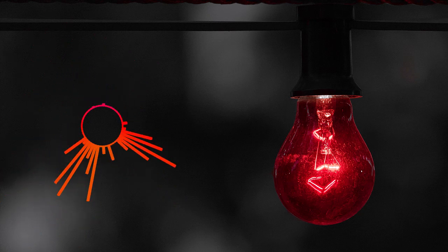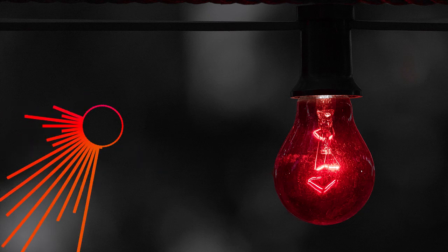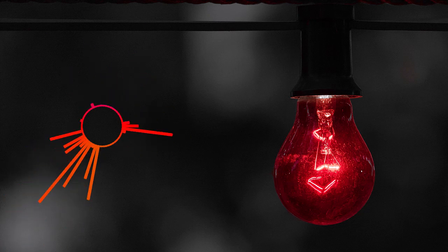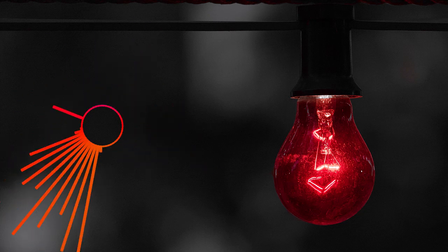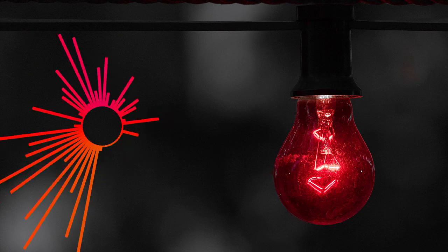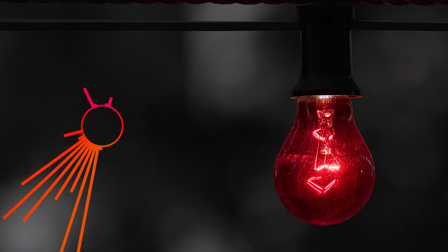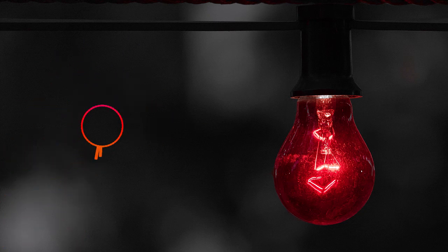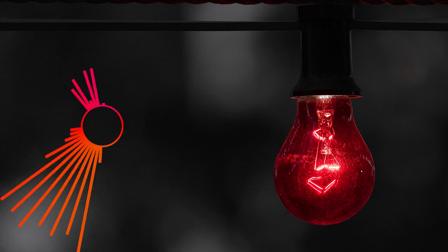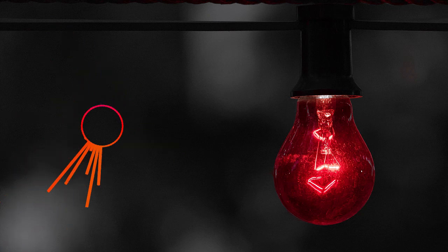Now, let's take a step back for a second. All of these control functions, on-off, occupancy, daylight harvesting, tuning, are part of automatic lighting controls. They rely on inputs like motion detection, time schedules, light sensors, building systems like fire alarms or HVAC. And best of all, they don't need a person to flip the switch. That is why they're so powerful.